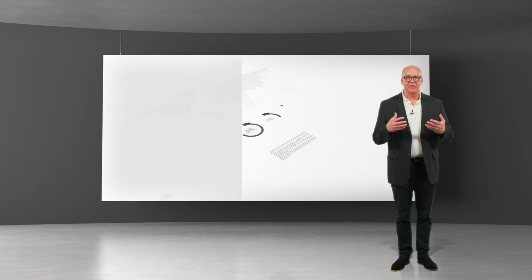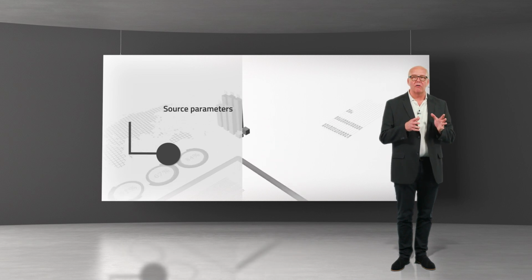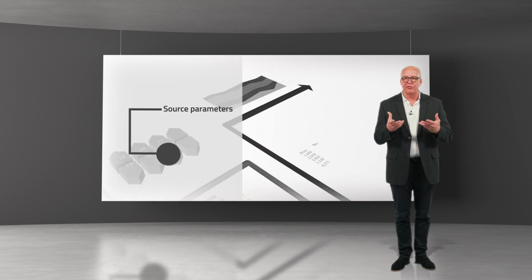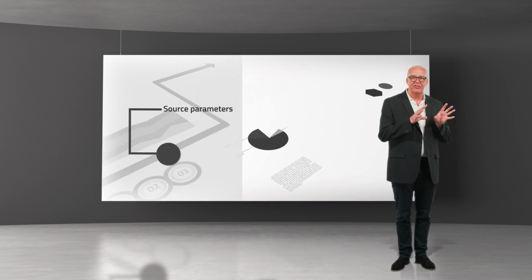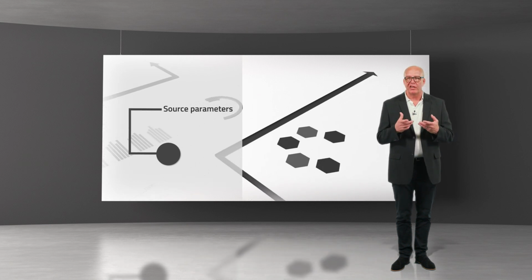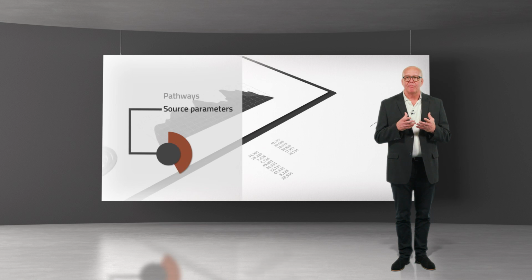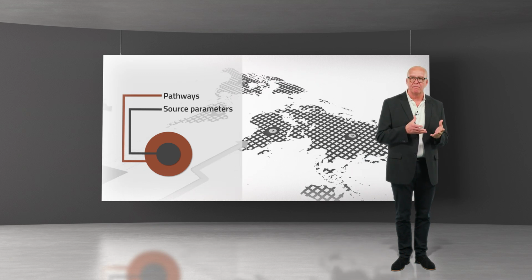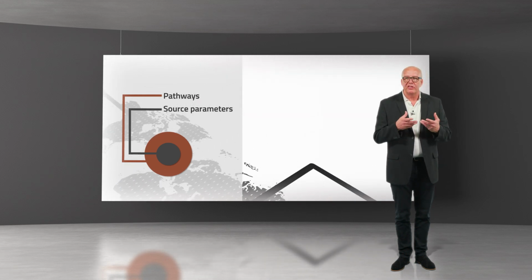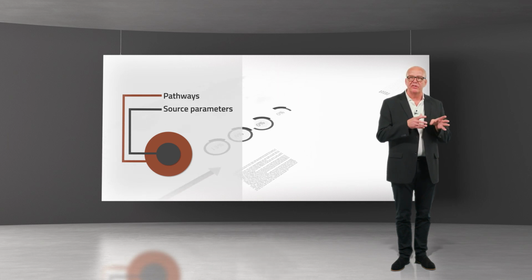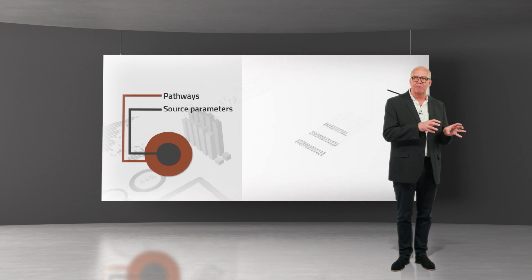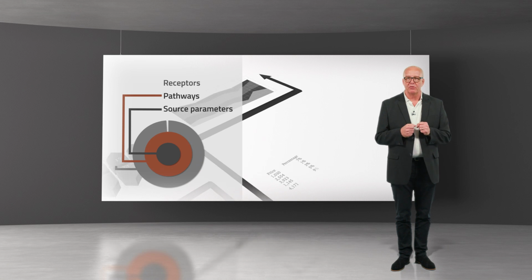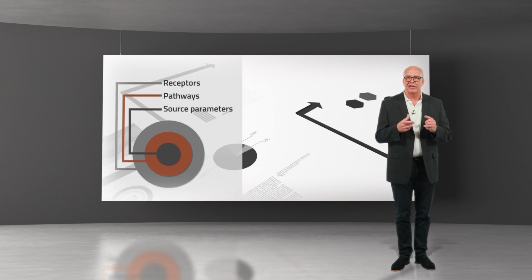The first step is site registry. That means you collect all facts about the site. This database includes an evaluation of all source parameters, like information about the size of the site and the type of waste disposed there. Facts about the environment around the site are evaluated as well. For example, about soil, surface and groundwater. This evaluation helps determine whether there are already existing environmental impacts caused by fires, leachate or landfill gas. The further surroundings of the site and their use are also analyzed.